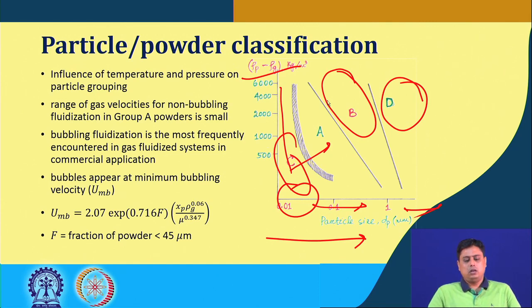So, a system that is non-fluidizing at a certain condition can be fluidized at a different operating condition. That operating condition can be changed with temperature and pressure, or some mechanical vibration or mechanical agitation. These are additional forces you can provide, such as a stirrer, or similar external forces, to make it fluidized. But this is the broad category at ambient condition based on their fluidization property.